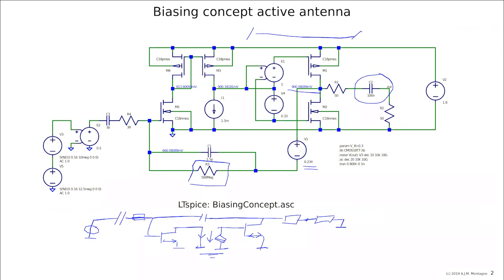So you see, in this circuit with biasing on what we call concept level, I have still floating voltage sources, one here for the class AB stage, and one here for the feedback biasing, and their implementation, of course, will be discussed next time. But this is what we think is like concept level biasing, ideal sources, minimization, so that you are ready for implementation and for setting up specs of these sources. That is basically the idea.